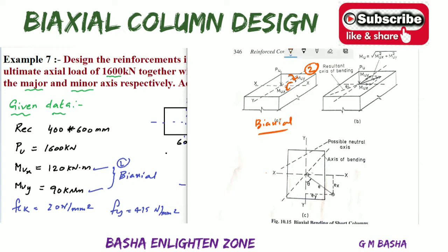Okay, so already I told you in the previous example, that is a uniaxial column acting at some eccentricity, only one additional moment is developed. So here, if you observe very clearly, there is an axial load which is acting exactly at the center, and if you want to find the moment, you can take a resultant moment, Mr, which will be equal to this formula: the square root of moment along x square plus moment along y square. And in the form of eccentricity you will get the resultant, it will be ex square plus ey square. At what distance the moment will be acting, each and everything will be shown clearly in this figure. You please observe this one.